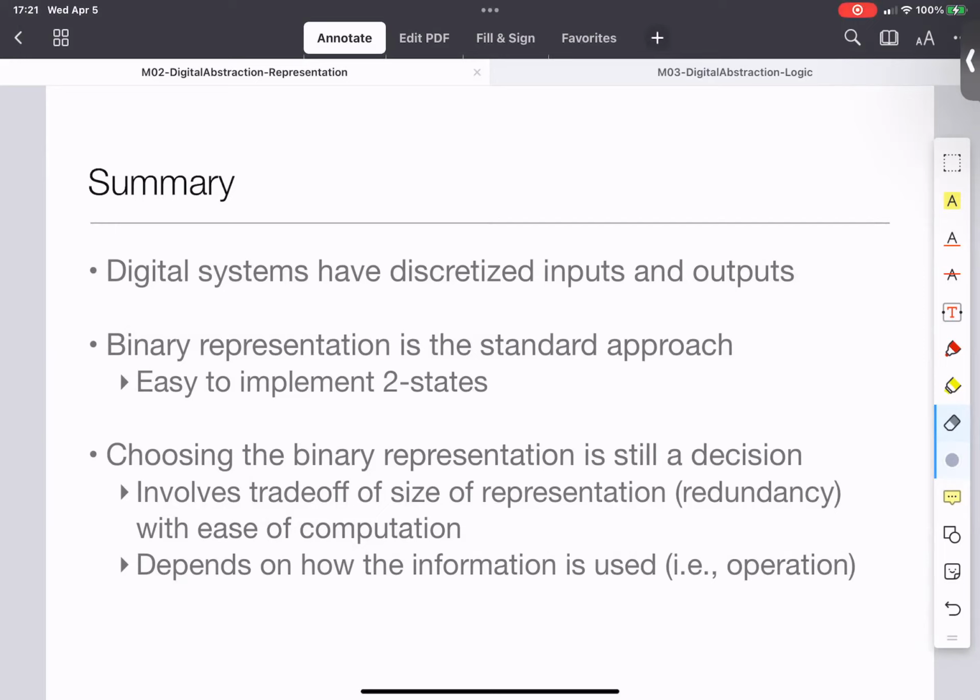I was wondering, you mentioned the Shannon theorem. Suppose we get some unknown signal, we don't know how high the frequency is, and we want to do some sampling at some fixed rate. Can we guarantee how much the error will be? No, unfortunately not, right? So what happens is there's a phenomenon called aliasing. So let's say you are wrong about what the maximum frequency component is. So now you are sampling at something which is less than 2 f max because you didn't know the correct f max. Then something called aliasing happens, where basically